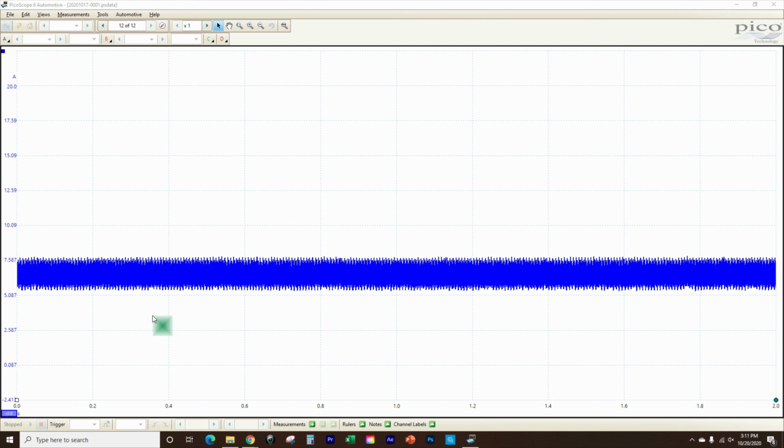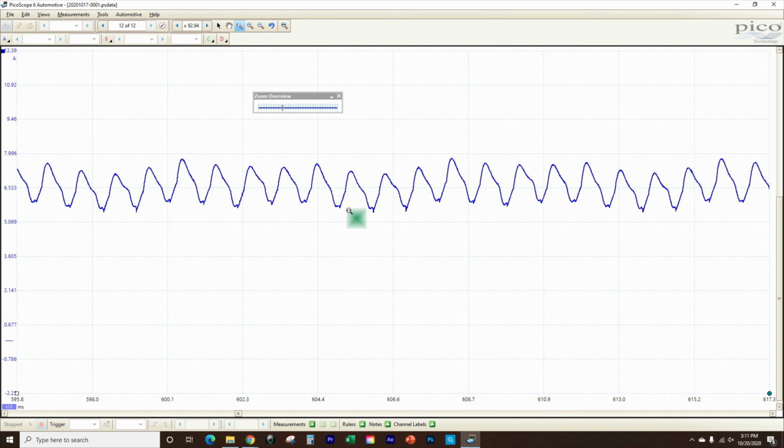This particular case was taken off of my Expedition. See one of the previous videos. First off, what we have to do is identify how many commutators this has and measure the time. We're not going to do it like this, so we're going to need to zoom in. So I'm going to pick a fairly small window here. All right, that's actually not a bad capture. You'll find the closer you zoom in, the better detail you'll have, the easier it's going to be to pick out your commutators. But now I'm going to look and see if I can identify something that's kind of similar as we go through here. See if I can pick out something that makes it easy to see.